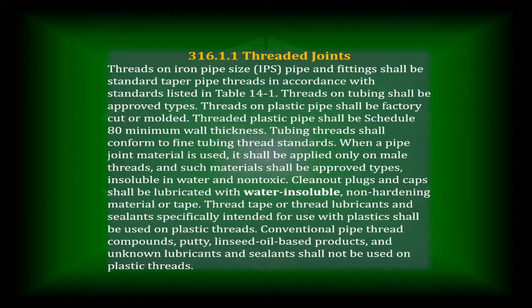So when we look at what we've got in our van, oftentimes we have one container of pipe dope. And when you're looking at threading compound or pipe tape, we often look at it as one style fits all types of pipe. That's not necessarily the case, and oftentimes it's not even close.